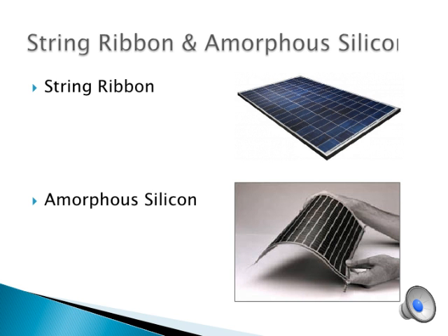Ribbon silicon is a type of multicrystalline silicon formed by drawing flat thin films from molten silicon. This method does not require sawing from ingots and therefore reduces silicon waste, which ultimately results in lower production cost. However, the efficiency of solar cells made up of ribbon silicon is relatively lower compared to the multicrystalline based solar cells.